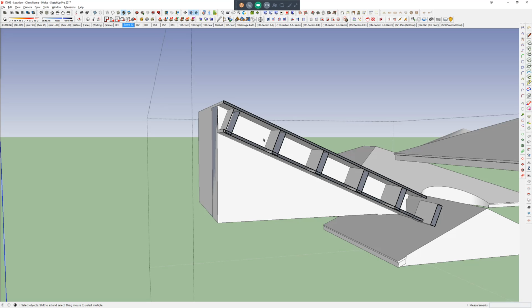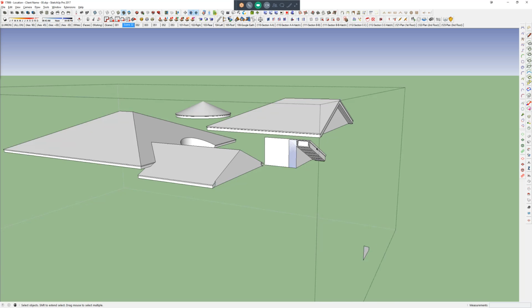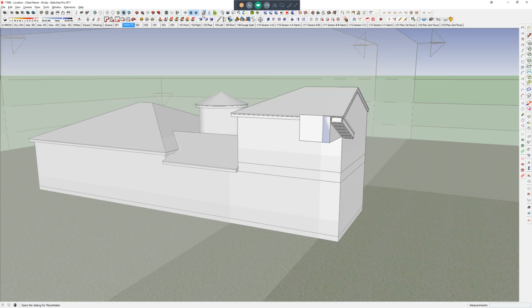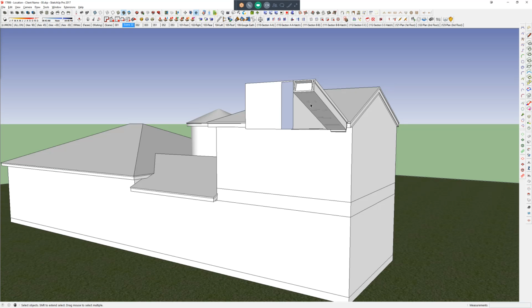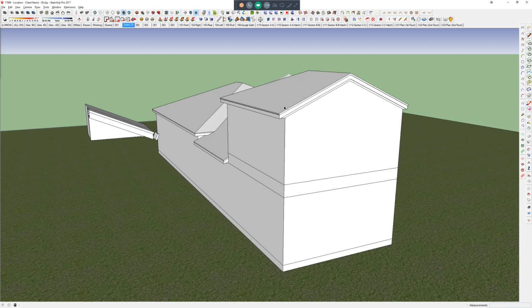Does that make sense? So that's if you're actually building a gable, versus what this is, where we're blocking everything out, or you're doing a zero overhang gable, which is literally just putting the truss up to the edge and then trimming it out. So that's really the two ways that you can make gables.